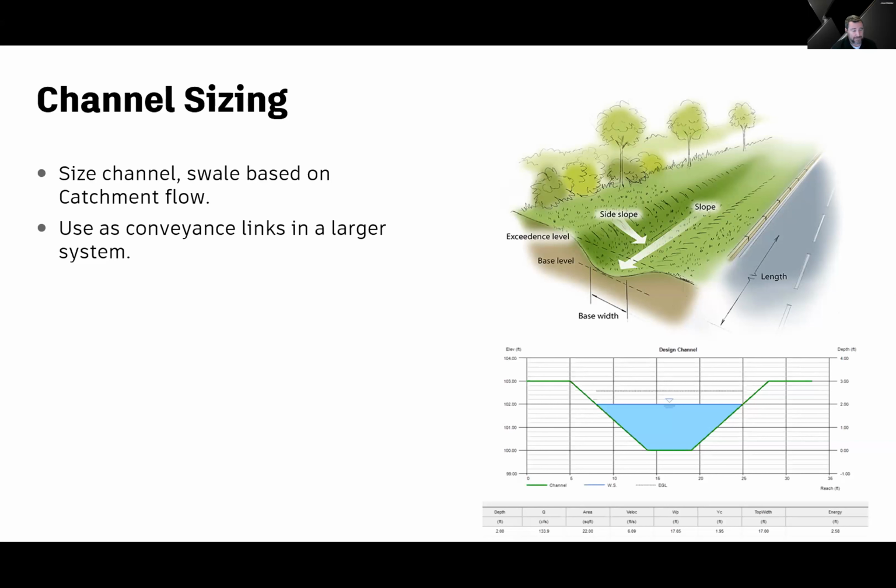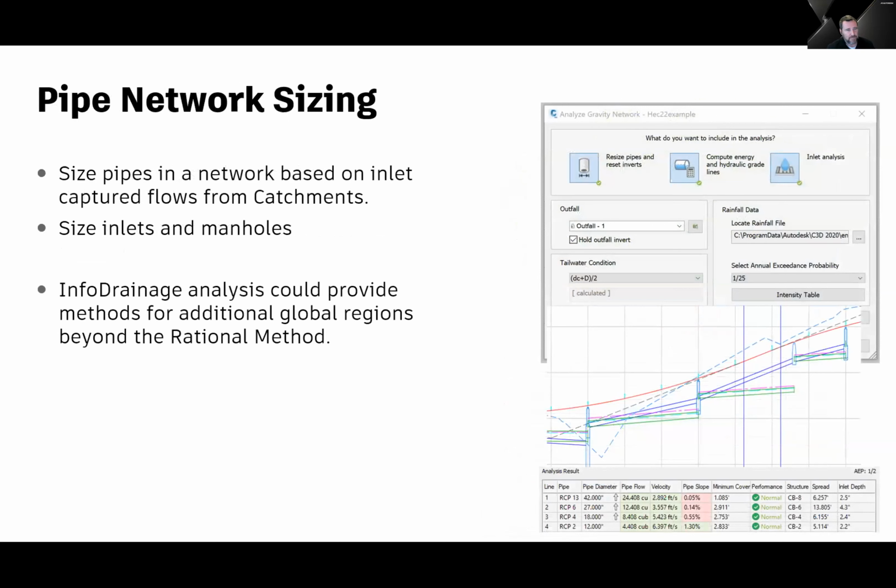So still, back to that pre versus post, everything's maybe not going through pipes, and you need some flow to go through channels, swales or whatever. And this is still probably important, even to be able to finish that pre versus post type of analysis. But again, here we're trying to see where to start. Do we start with being able to model a channel, or being able to model the storage, like I mentioned before? That's what we're trying to figure out.